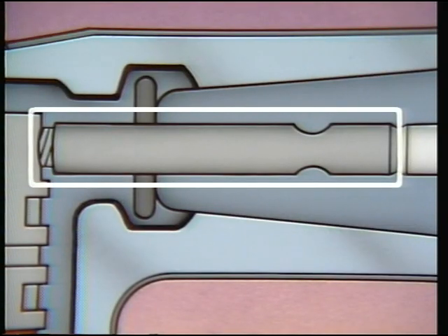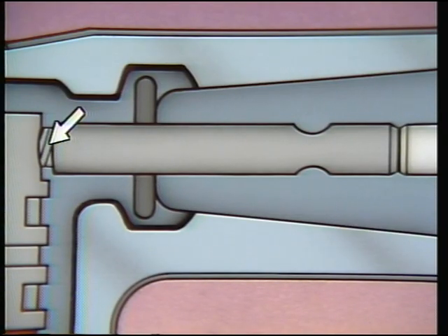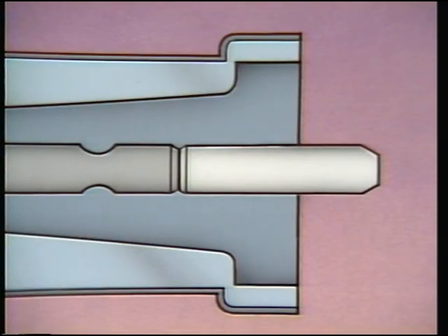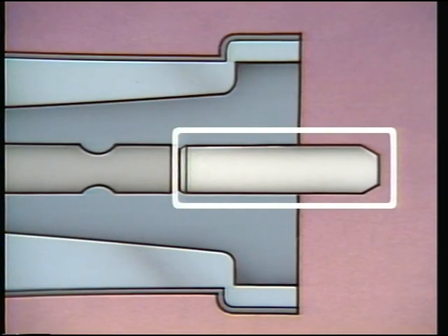The male probe contact is where the elbow is connected to an equipment bushing. One end of the contact has a threaded screw, which is used to hold the contact in the elbow. On the other end of the male contact is a plastic tip, which serves as an arc extinguishing device when the elbow is removed from equipment under load. The non-load break elbow has a similar construction, but its male probe contact does not make an electrical connection between the cable connector and the electrical equipment. Instead, the internal parts of the non-load break elbow are mechanically bolted together at the contact points.